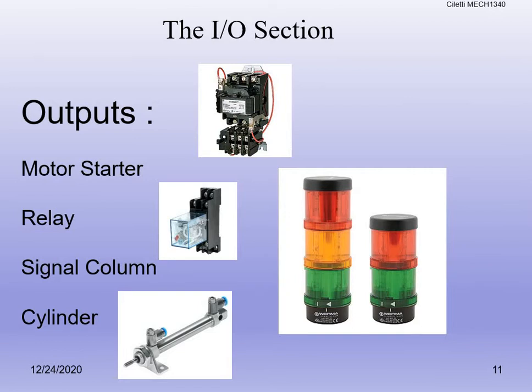Those are going to be tied more through solenoid valves, though, as far as how we're going to control those cylinders, because the cylinders are pneumatic, but we can control the solenoid valve that opens and closes the plunger that allows the air to flow one way or another through the control valve. So in a roundabout way, we use the solenoid valves to control the directional control valves that control the cylinders.